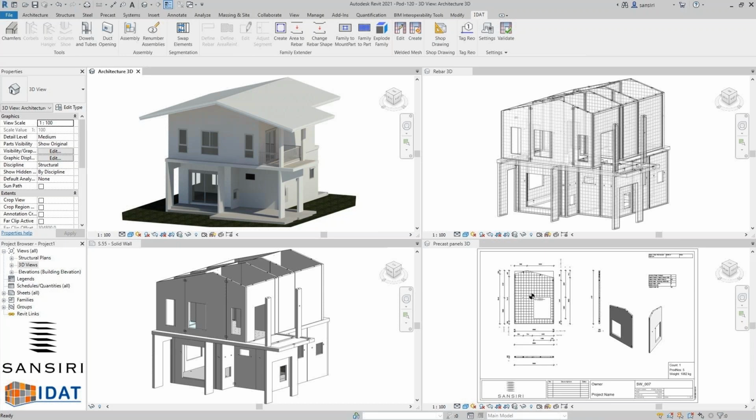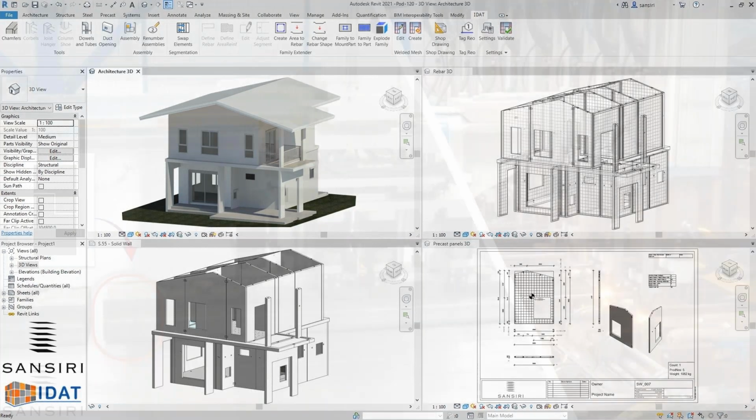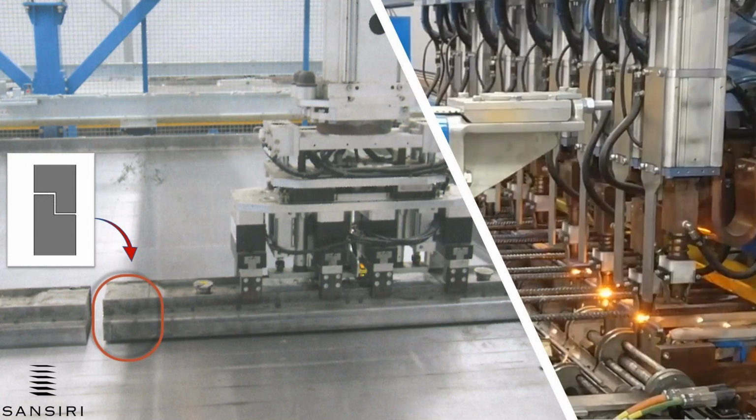And what that customization means, in this case it was especially the CAM files, so the type of information that needed to be included in the files that are used by the industrial robots. And one example is how the chamfers need to look. In this case, you see here there is this detail on the types of chamfers that the factory needed to have, and of course this information needs to come from the model. So you need to model the panels using such chamfers automatically using Revit.